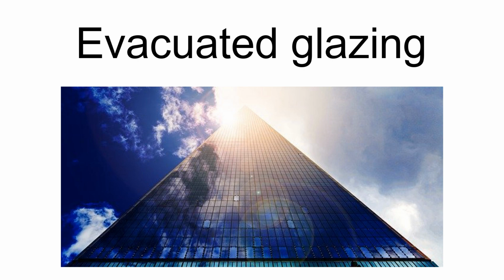An evacuated glazing unit is made by sealing the edges of 2 glass sheets, typically by using a solder glass, and evacuating the space inside with a vacuum pump. The evacuated space between the 2 sheets can be very shallow and yet be a good insulator, yielding insulative window glass with nominal thicknesses as low as 6 mm overall. The reasons for this low thickness are deceptively complex, but the potential insulation is good essentially because there can be no convection or gaseous conduction in a vacuum.